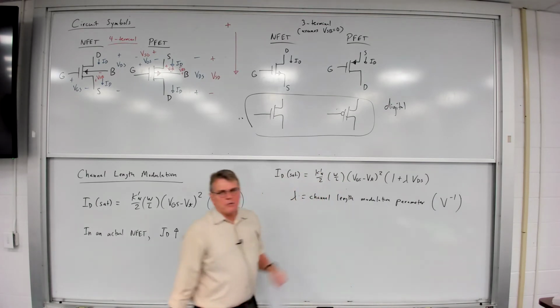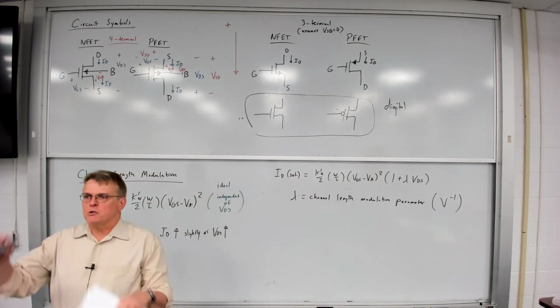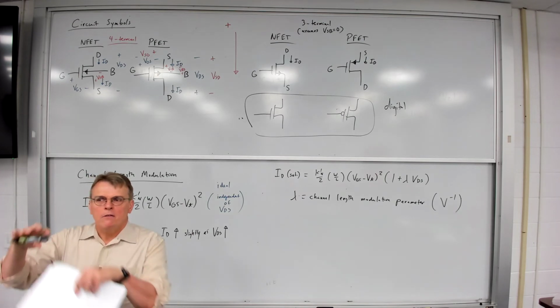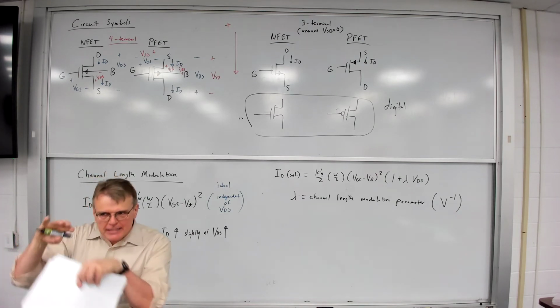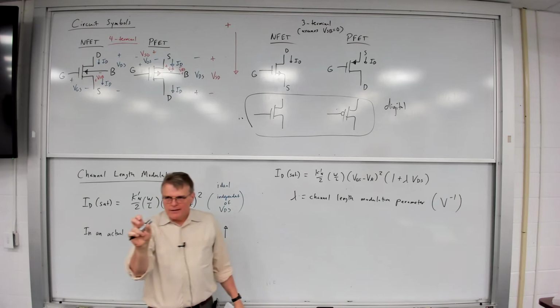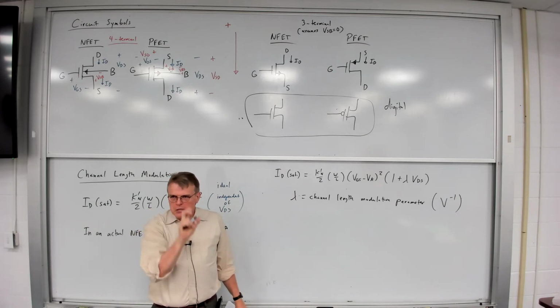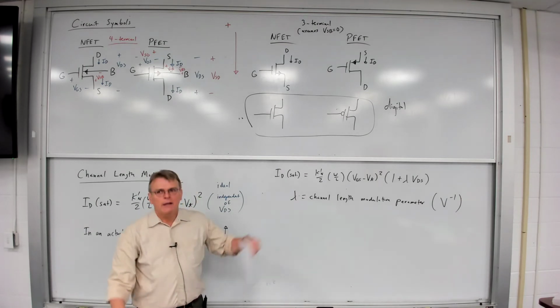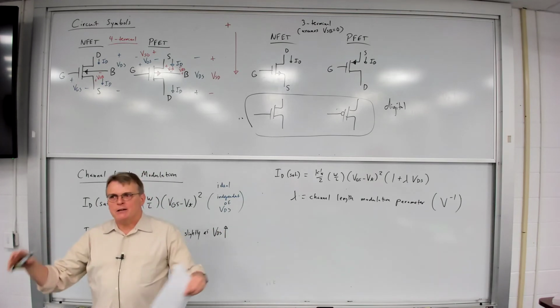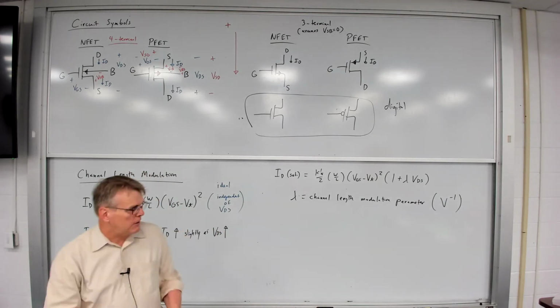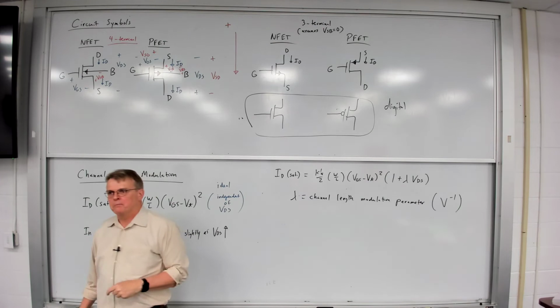Now what does this show? This simply illustrates that as our drain becomes more positive, the geometry of the channel is affected. Even though we're pinched off, ideally once we pinch off, the channel geometry shouldn't change, but actually there's a second order effect that does cause it to change slightly. And so therefore we get this current term.